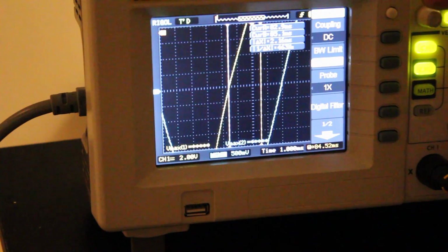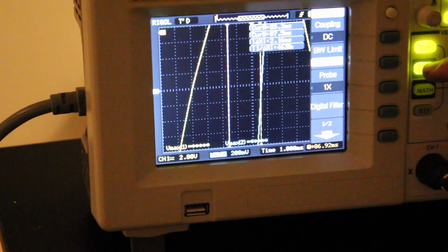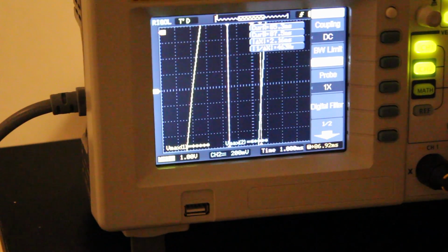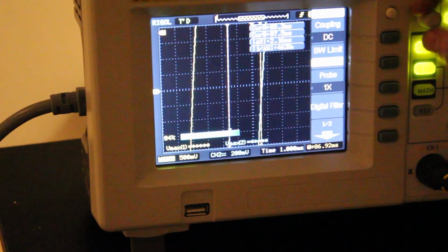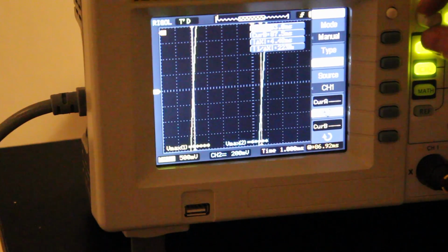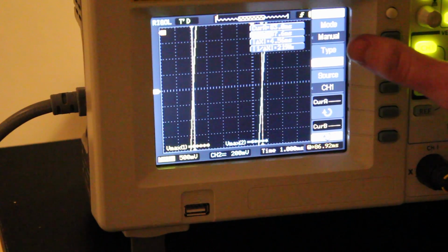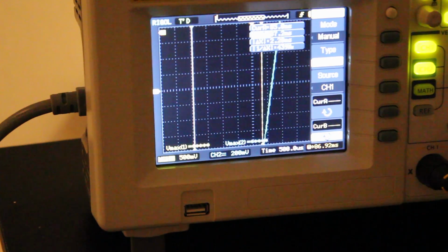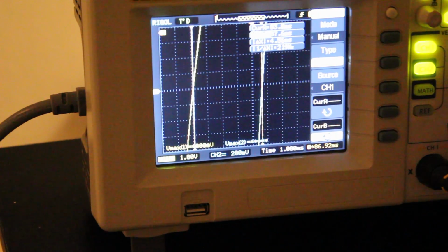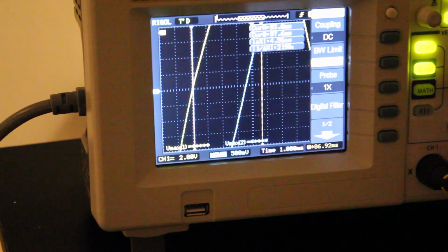I'm going to do this a little bit more slowly. Okay. So that's pretty good. Now we can even bring up channel 1 a little bit more. All right, now we'll use the cursors. And let's see if we can't figure out what that delay is. Check it out. So we've got a delay of about 4.56 milliseconds. In fact, I think that's a little off. I don't think I'm quite at the crossing point. Okay, yeah, I was a little off there.